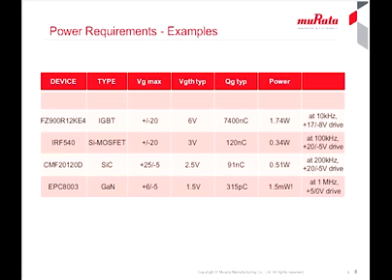It is dissipated in the internal gate resistance in the device and in any extra external resistance that is introduced, and some is for sure dissipated in the driver transistors. MOSFETs generally have lower gate charge than IGBTs, so the calculated power can be much lower. However, MOSFETs can run at much higher frequencies than IGBTs, so we do see MOSFET applications at high frequencies where many watts are still needed because of our equation. Power needed is proportional to switching frequency.